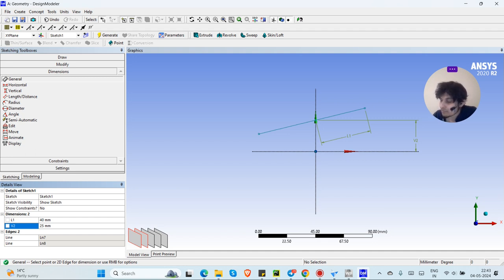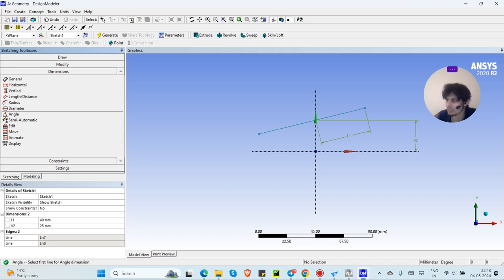Click the create the blade, sketch continues, and from the dimension toolbox select the angle. Yeah, I was wondering why are we not setting an angle here. I could make it any angle and it could start depropelling me instead of propelling. Okay, from the dimensions toolbox select angle, and I think we must be setting an angle with the x-axis. That's what I'm speculating. Right click and select alternate angle until the correct angle dimension is shown, and then click to position the dimension.